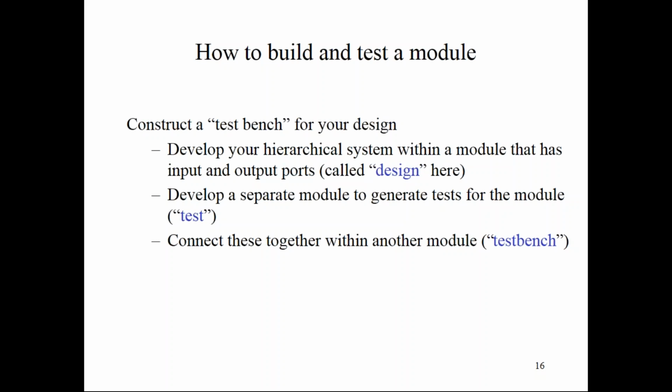So in that you have to design a hierarchical module. Then with that you have to give the input and output ports. That specification is also called the design. Then a separate module is used to feed the inputs to our design. That is actually called the test bench. And the inputs and outputs we define in it are the test cases.